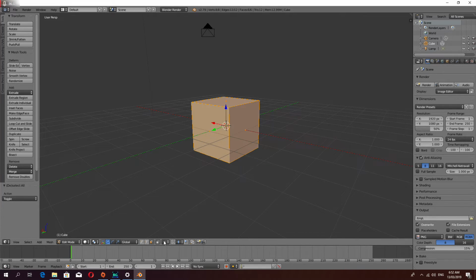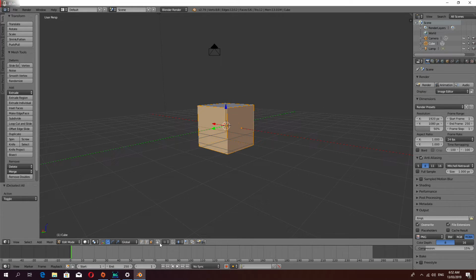But another tool that you can use is this one here. So this limits the selection to visible. So when you select something, it only selects the visible things. You can tick it, you can untick it, and you'll see now that I've got some little dots showing through here. It's not quite wireframe, but when I make a selection, it does select the things through there. So if you don't like working in wireframe because it's a little bit confusing, you can turn this off, and that will let you do some selection.